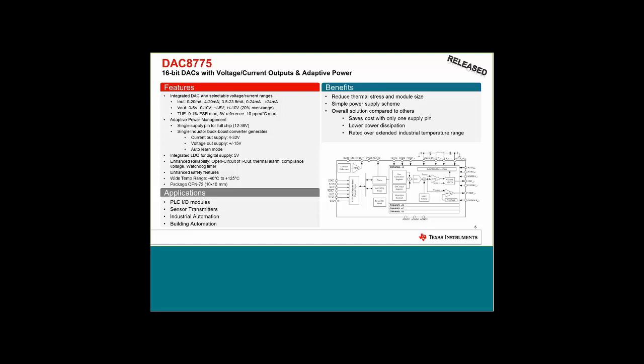So basically then, with this capability of the SIMO DC-DC coupled with an internal 5 volt LDO for the digital supply, suppose you're implementing digital isolation, you need a supply voltage for the hot side of the isolation scheme. We can provide that from our device, and a 5 volt, 10 ppm per degree C reference. So basically then, from a single input supply, we can generate plus minus 5 volts, a 5 volt digital LDO, and a 5 volt reference, which is everything that our device and the hot side of the system needs in order to be operational.